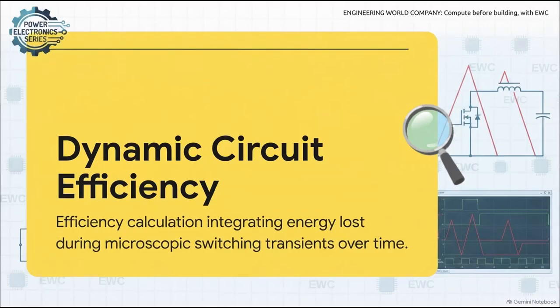And that brings us to a really critical concept, dynamic circuit efficiency. Basically, this is an efficiency calculation that actually integrates the energy lost during these exact microscopic switching transients over time. It's essentially calculating the geometrical area of those red voltage current power spike triangles we just looked at, multiplying it by the switching frequency and adding it to your baseline conduction losses. If you aren't accounting for dynamic efficiency, your thermal management calculations are going to be wildly inaccurate.